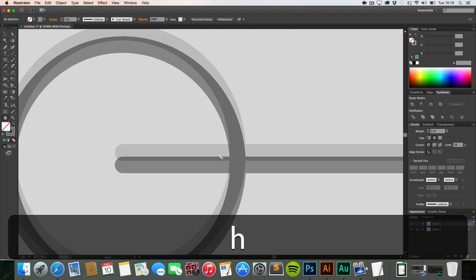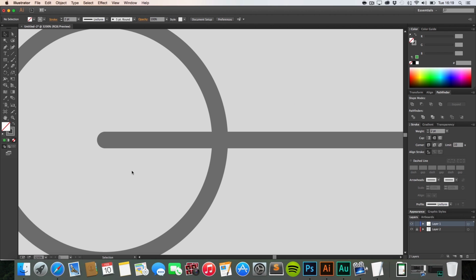But this time you can see we can't delete it since, well, we could delete it by transforming or by expanding this shape and expanding this shape, then subtracting this inner shape from our path right here, but that's way too much of a hassle. Just grab your path, press C to get the scissors tool.